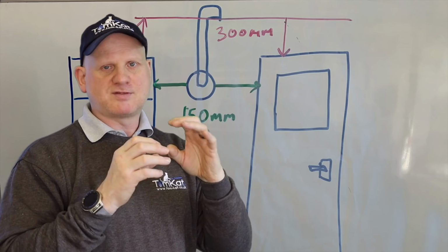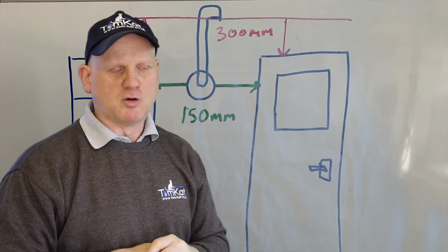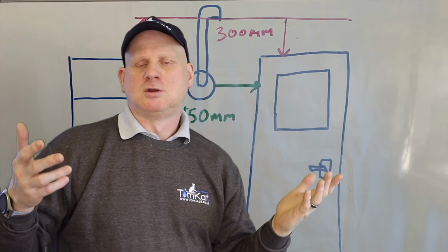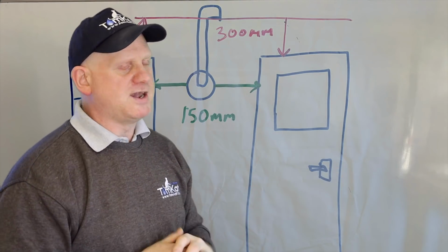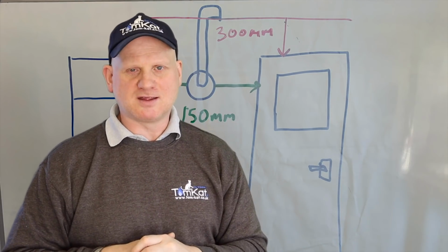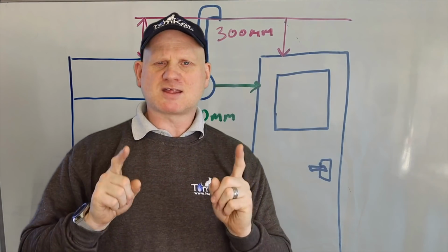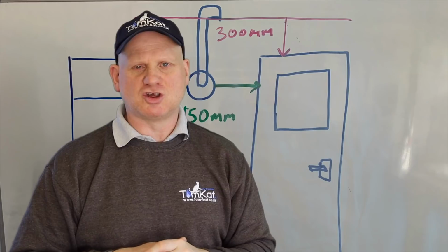That's the flue length plus 300 above, not 300 above the actual flue itself, it's above the window. So not every manufacturer allows you to do this, so it's important and imperative that you do check this. So let's have a look at more measurements used for Plume Management Kits.